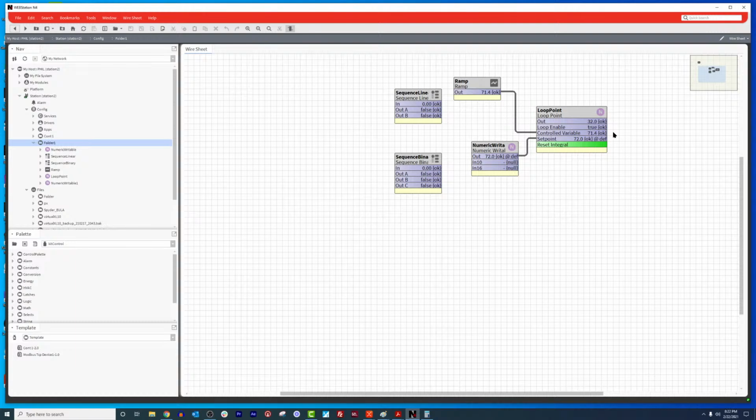That's not proportional. So if you are ever below set point on a direct acting loop and you still have output, you most likely have integral windup. That's what's going on, and you need to adjust your I value. That's what I tell folks when they ask, how do I tune my loops? I go to this job site and the loop is not performing. What do I do?